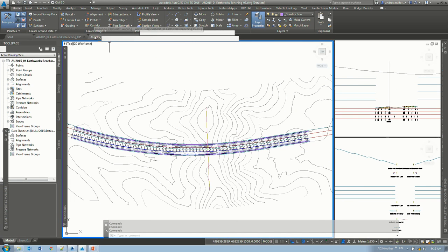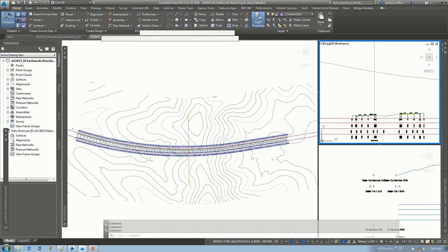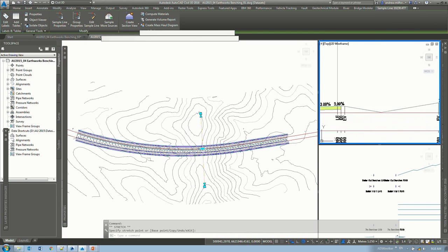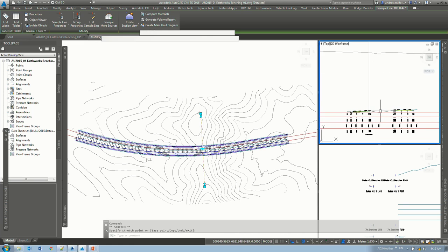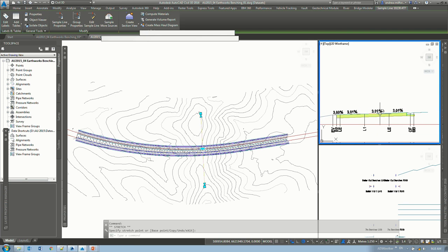Okay, so the first part of this, let me just get to the right drawing here. We're in drawing 1. You can see here there's a quick cross section we have. It's actually pretty deep. The main roadway has already been designed, just using standard Civil 3D corridors. We've got some median, 10:1 median slopes sitting in there. Actually, I think they're 6:1s.